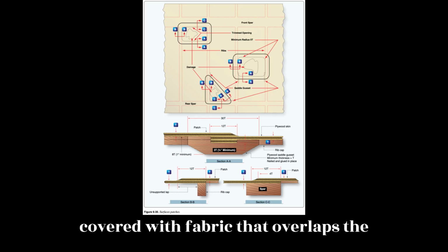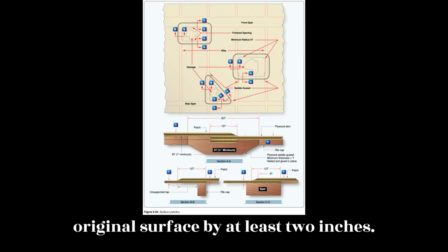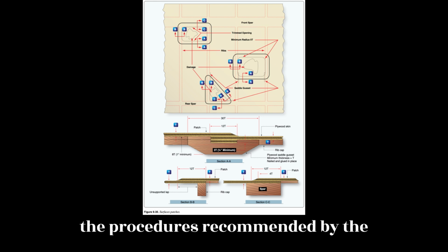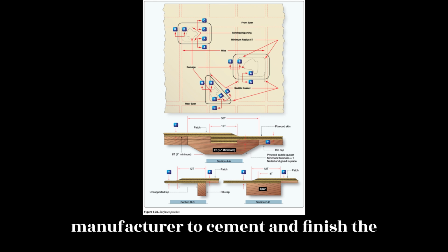The patch should be covered with fabric that overlaps the original surface by at least 2 inches. The fabric should be from one of the approved fabric covering systems, using the procedures recommended by the manufacturer to cement and finish the fabric.